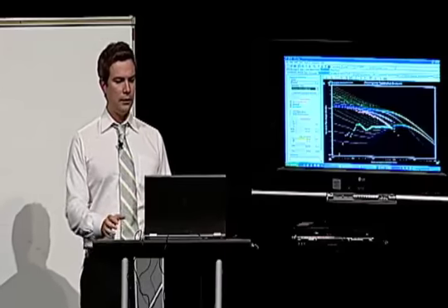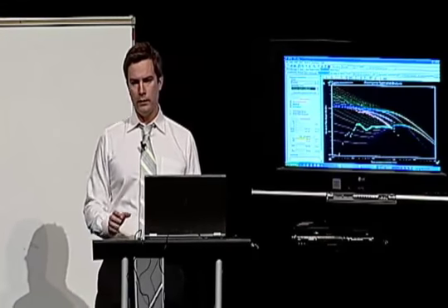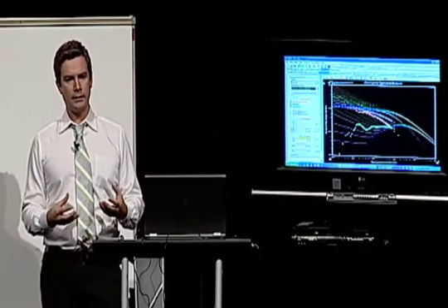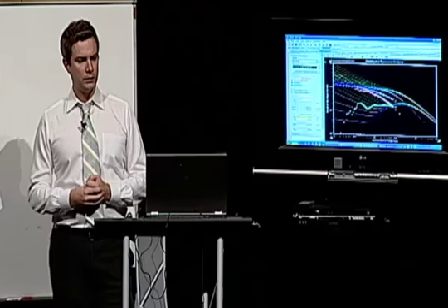One of the advantages of doing something like RTA is that the data is being collected and it doesn't cost you anything extra. When we compare this, for example, to a planned pressure transient analysis, like a flow and buildup test, it makes a lot of economic sense to do rate transient analysis. The data is free. It's being collected as a matter of good production practice. We should analyze it and get as much value out of it as we can. So it makes very good practical sense in the absence of a well test to do this sort of work.